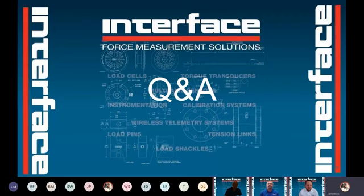I would just add, use caution in the bridge amplifiers. These are ratiometric sensors, so any noise that may come through on the supply side will impact the signal. So quality of instrumentation is really important.